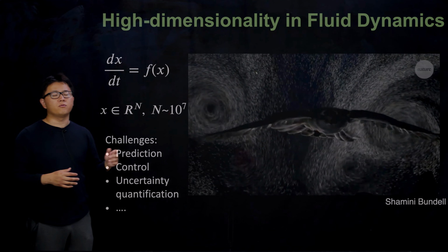But if you're looking at these particles, although there are so many of them, they seem to obey some low-dimensional structures. Therefore, it induced the idea of can we find a low-dimensional latent representation, x hat, maybe just 10 dimensions, but good enough to preserve the dynamical behaviors in high dimensions. Okay, so this is the task called dimensionality reduction in fluid dynamics.